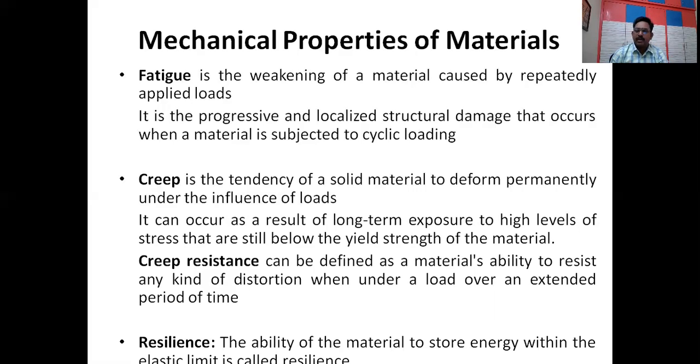When a load is applied, the material will deform, and when the load is removed, it will bounce back to its original shape. Up to a certain load only will it regain its shape. Up to that point, we call it the elastic limit. So the ability of the material to store energy within the elastic limit is called resilience.